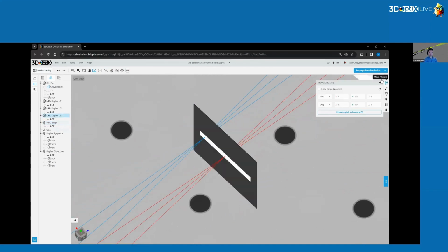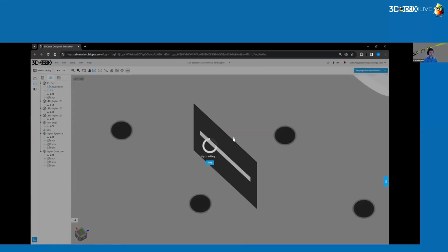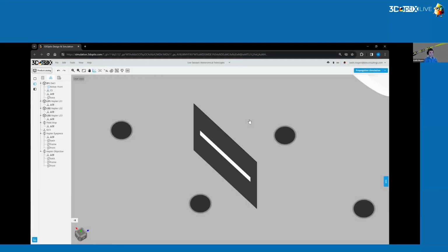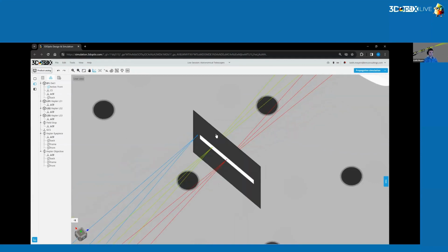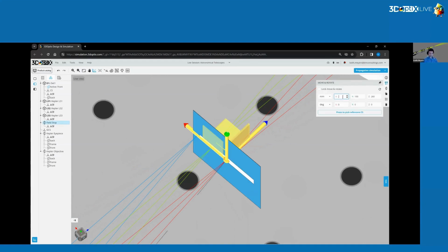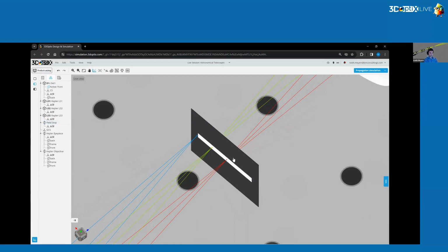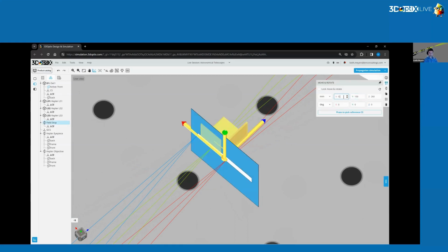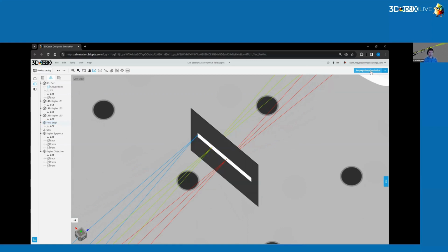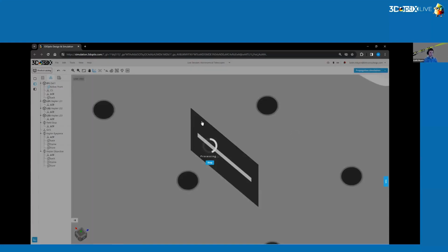Before we do that, we want to extend our field out to 2 degrees. We'll re-propagate the simulation, and this will allow us to have a 2-degree field of view. Okay, so we need to move the aperture out a little bit. Move this to 0.6. Maybe a little bit more. And again, we want to block that chief ray. This will allow us to get about 50% of the illumination at that field angle through our system.